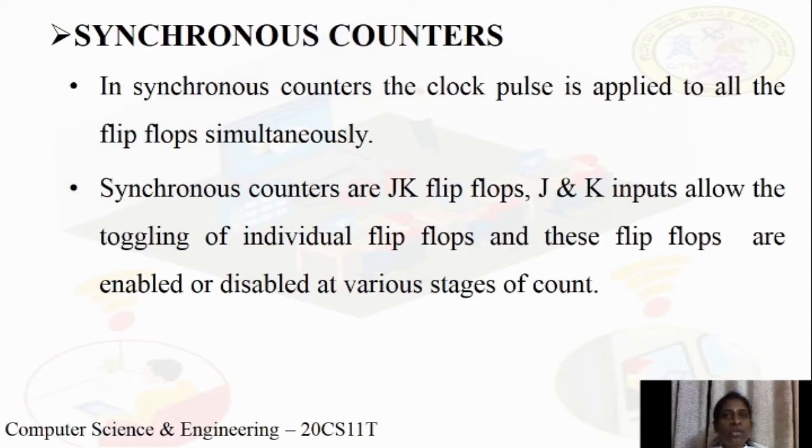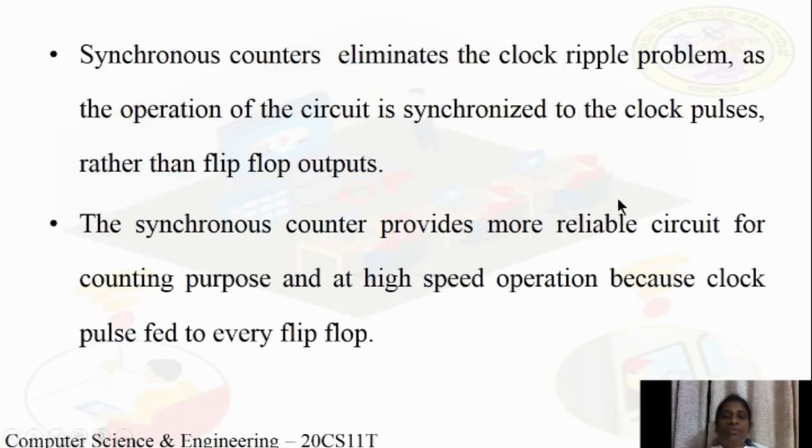Because of this, the ripple problem present in the asynchronous counter will be eliminated. These synchronous counters are designed using JK flip-flops. The JK inputs allow the flip-flop to toggle from one state to another by enabling or disabling the various stages of count.